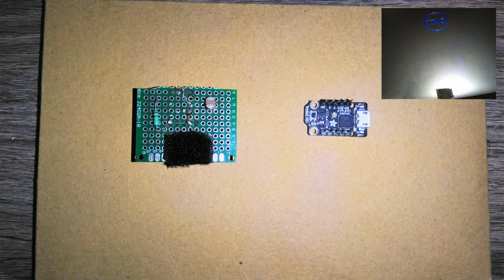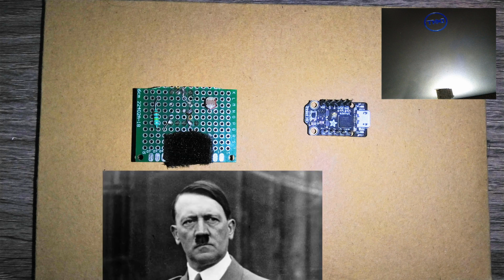And so then I built the voltage divider circuit on the general purpose PCB, and also soldered the female headers on the general PCB and the male headers on the Adafruit Trinket board. In order to mount the circuit onto my laptop, I used a piece of Velcro both on my laptop as well as on the board. I know what you guys are thinking. I'm not a fan of this man, but unfortunately the Velcro that I used resembles this guy's mustache.